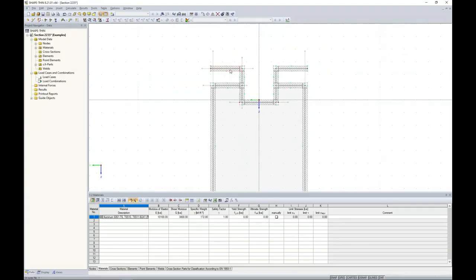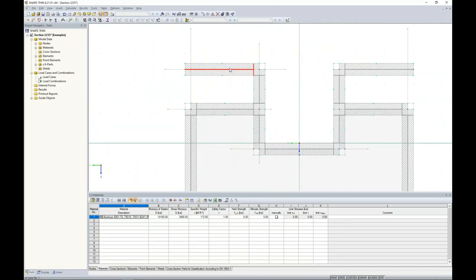Now, you'll see these symbols at each element, and these are the width to thickness symbols, those C over T parts. So this is what's recognizing width to thickness, but even more so, you'll notice that at these closed ends, we have what looks like a T symbol, but at the open ends, we don't have that same symbol. So this, again, is important for aluminum design to tell the program how the edges are supported. And over on the right hand side, we can see that it's supported, but over on the left hand side, it's not supported. Again, important for local buckling.